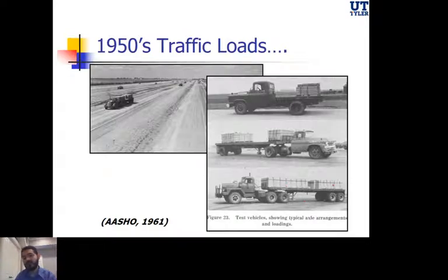But as you can see, they tried to put uniform load, and all they did afterwards was keep driving these trucks over and over on those sections until they failed. So it's pretty much accelerated testing to apply the amount of ESALs, the equivalent single axle load that will be experienced by any road in 15 years. They did it in about 6 months in order to accelerate the testing and to know how much this pavement will last before it starts to fail.